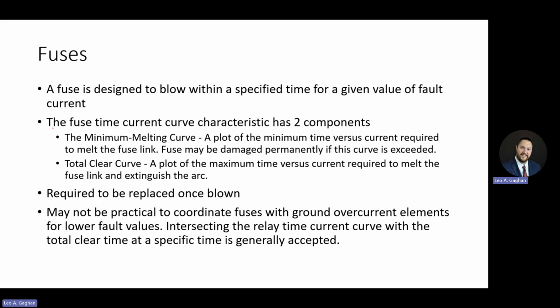So they need to be set up above loading. And a lot of the times it's not practical to coordinate these fuses with other ground elements in the area which operate off of the imbalance, because those guys are set more sensitive than load. Sometimes it's challenging to coordinate fuses with the ground overcurrent elements in the area.